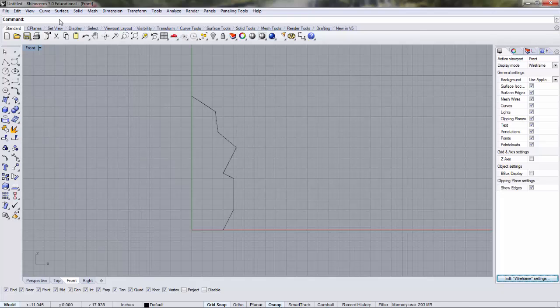So if I want to ungroup those, I can type ungroup, and you don't have to actually have your cursor or pointer up here. You can just type in no matter where your pointer is. I'm going to do ungroup. So I have to select the objects and then hit return. So now see they're all individual again.